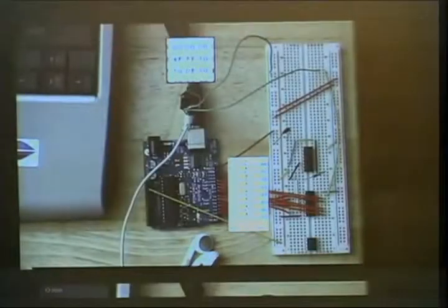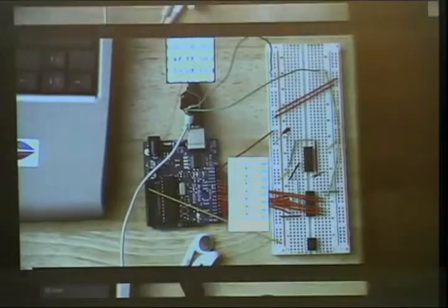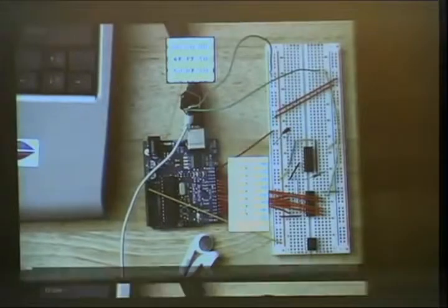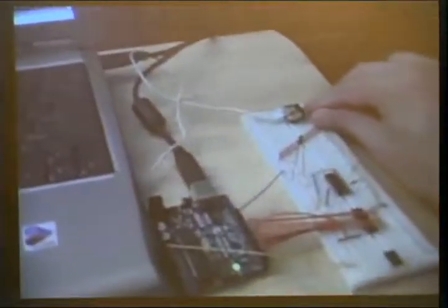So that's the first prototype I did, was to stream a VGM file through serial port, send it to the Arduino, parse it out into the 1s and 0s, and send it to the PSG chip. I got this idea from Little Scale, this website that did a similar project. And here's a video of it playing. So from my computer, the VGM file streams to the serial port, USB.